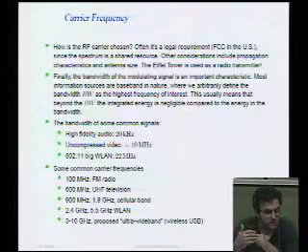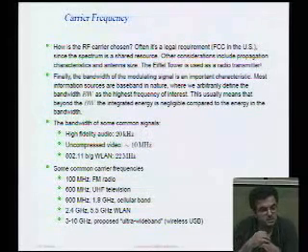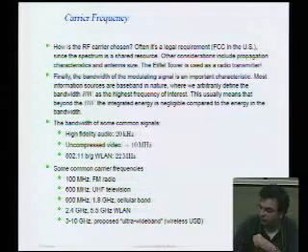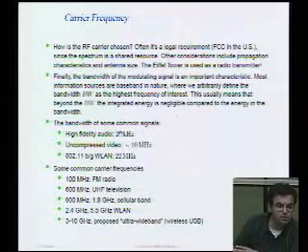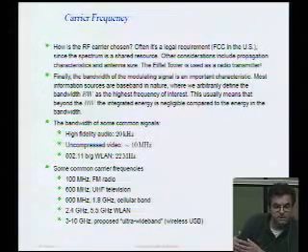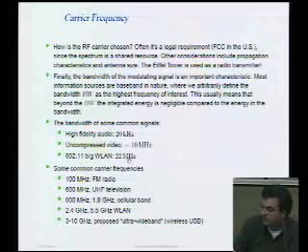So generally, the higher the data rate, the higher the frequency, because you can have more channels. And I put down some numbers here. High fidelity audio is about 20 kilohertz of raw bandwidth. Now if you modulate that linearly onto a carrier, the bandwidth doesn't change. So if I just AM modulate, bandwidth's about the same. If I do some kind of nonlinear modulation like FM, there's actually a big bandwidth expansion. I need about 10 times more bandwidth.